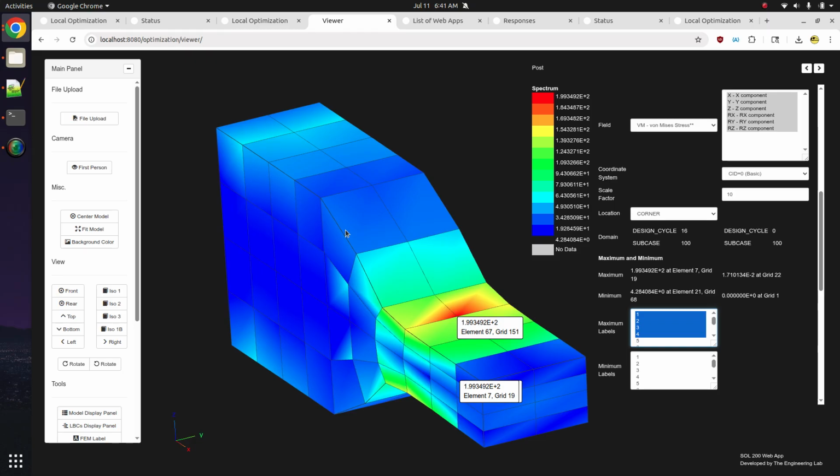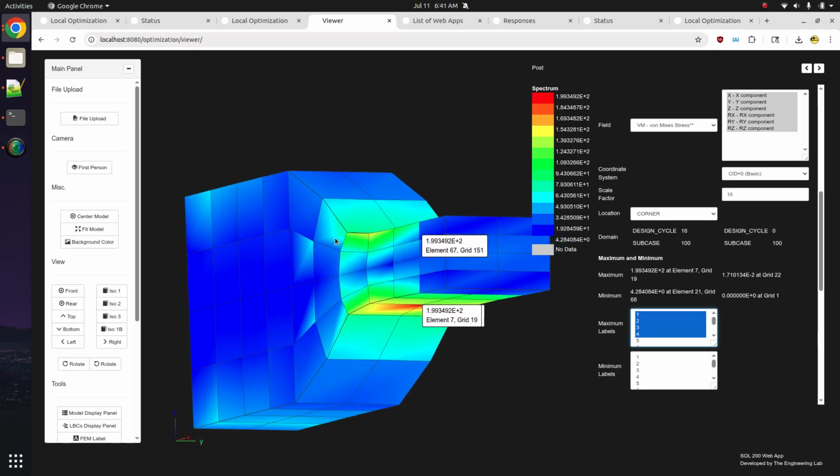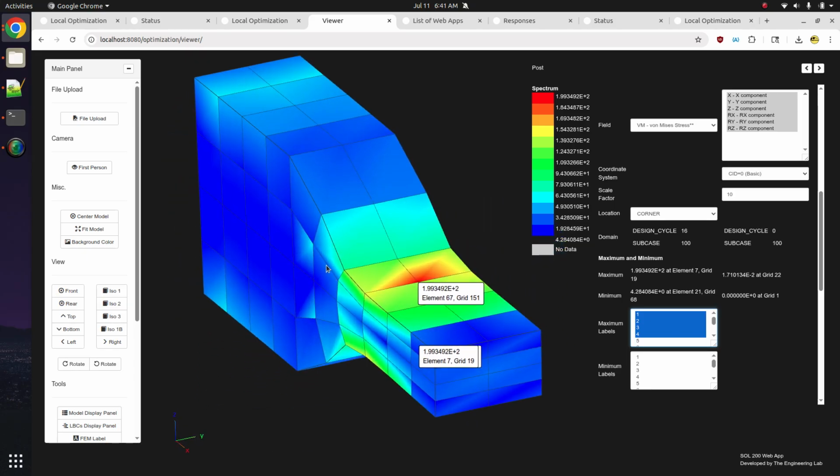Now, I should mention that one of the motivations in trying to minimize the maximum stress is you're trying to achieve what's called a fully stressed design. This is where you have as many elements as possible being equally stressed. When you have as many elements as possible equally stressed, you're efficiently using your material and your structural design. Now, for this example, that's not possible.